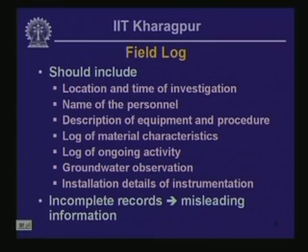Then there should be groundwater observation, whether the water flow, or water used in the progress of the drill hole, that actually is lost within a cavity, that also should be mentioned here, water loss.